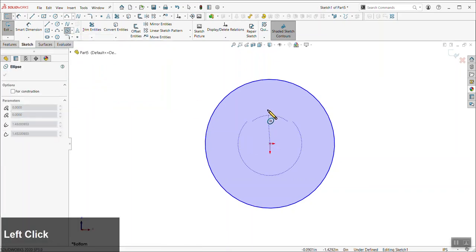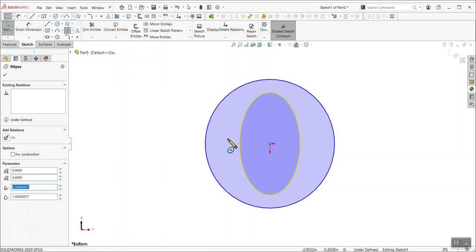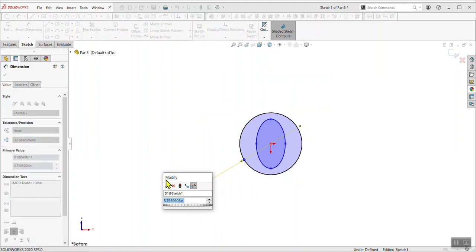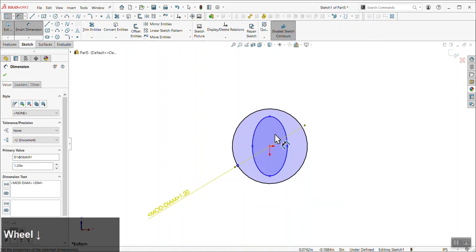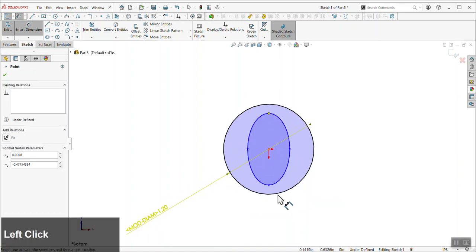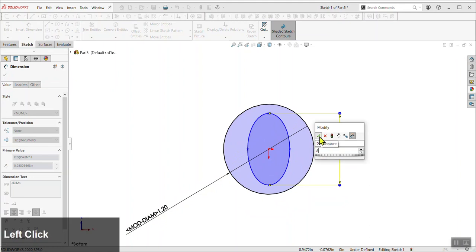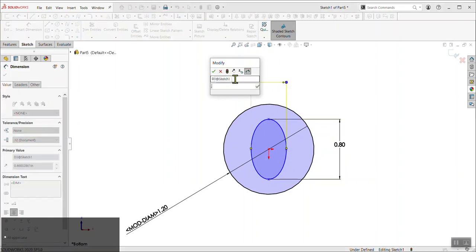And again, I'm going to click on the center, and the ellipse requires three clicks. The starting point is the center, then you set the height and the width. So now I'm going to dimension this to match our intended demo here. The circle will be set to 1.2 inches in diameter. The height of our ellipse, which we should have two endpoints to select, will be 0.8 inches tall, and the width will be, if we select the two points side to side, 0.4 inches wide.